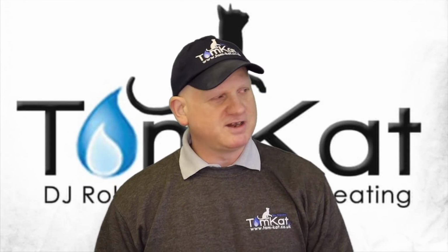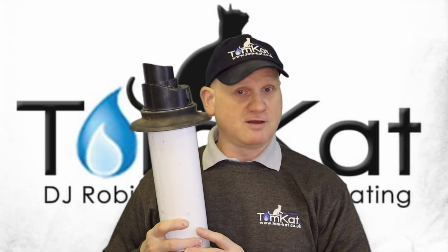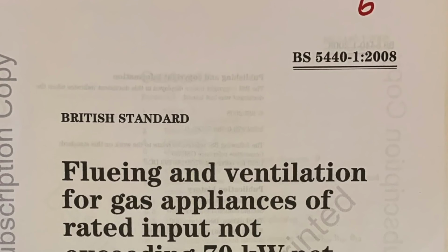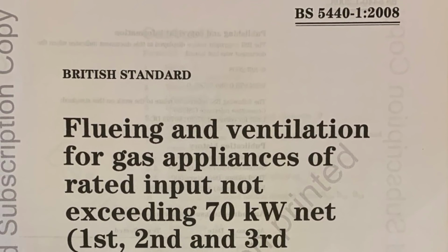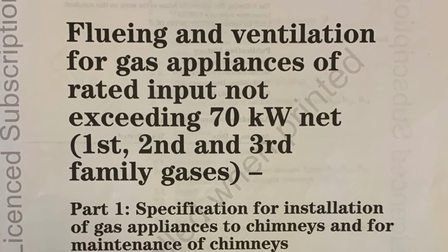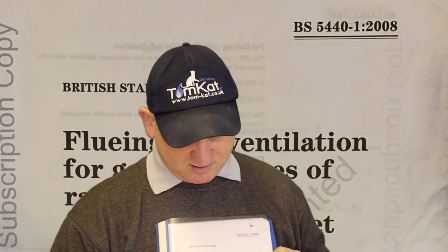Now, first part of this video, we're going to look at all the regulations when we're installing the flues. The regulations we're going to be working to when we're installing these room sealed appliances, we're going to be using BS 5440 Part 1. And this is the fluing and ventilation for gas appliances of rated input not exceeding 70 kilowatt net, first, second and third family gases. So that is BS 5440 Part 1.